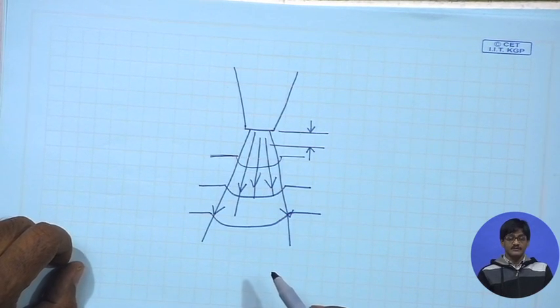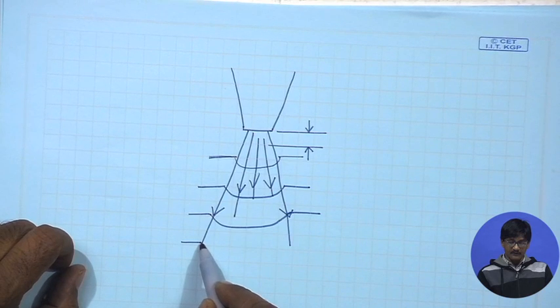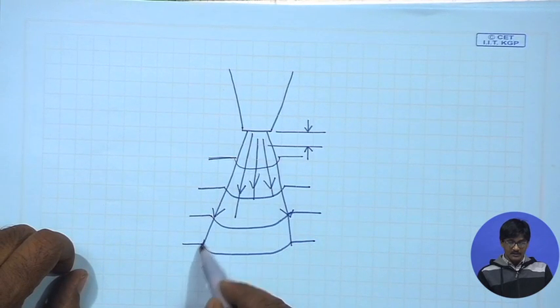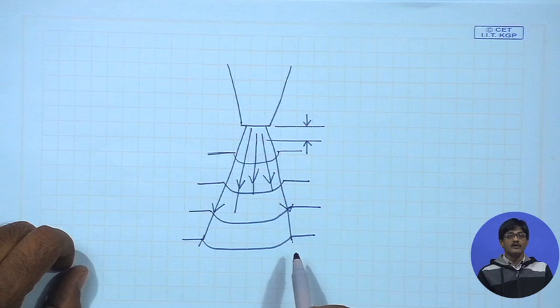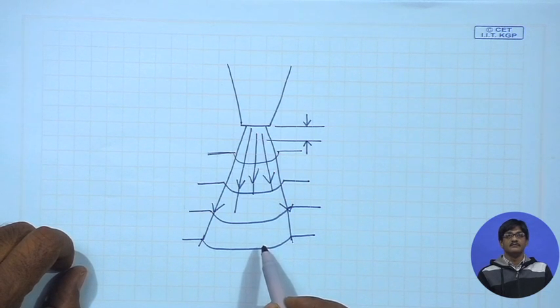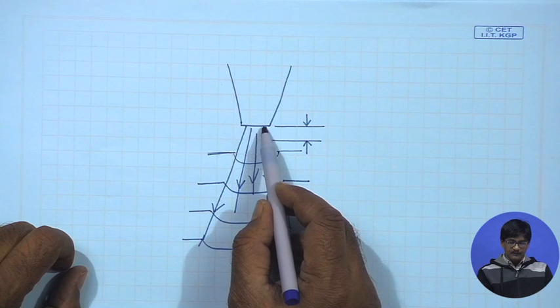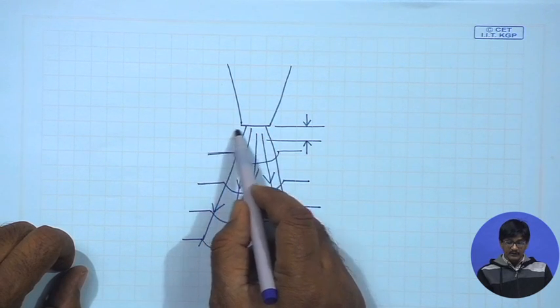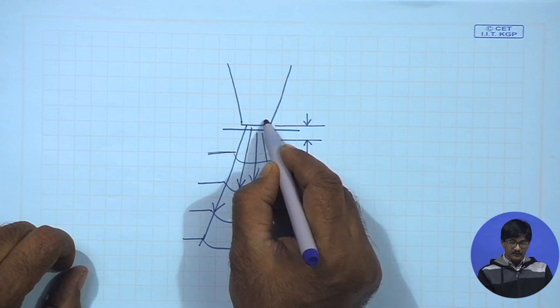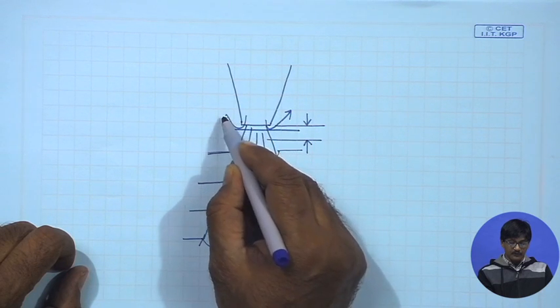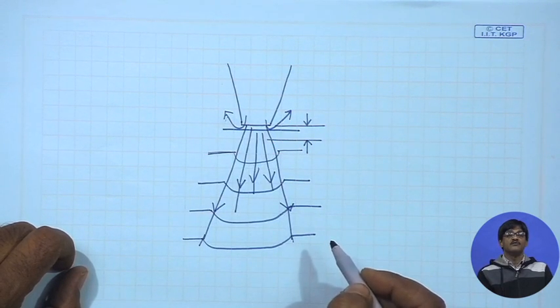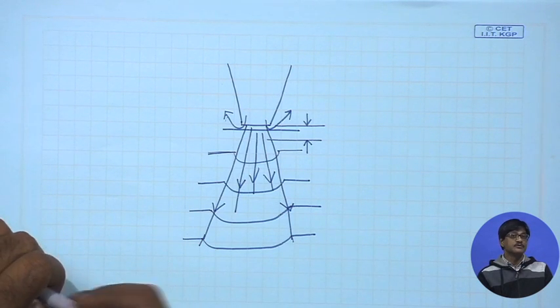But after some time you will find that the velocity of the particles becomes so less that they cannot create plastic deformation on the body, they will simply bounce off ineffectively. So, after some time material removal rate will come down. So, if the distance is very small, in that case back pressure will be created, the abrasives will not be able to come out at all, and therefore material removal rate will be very low.